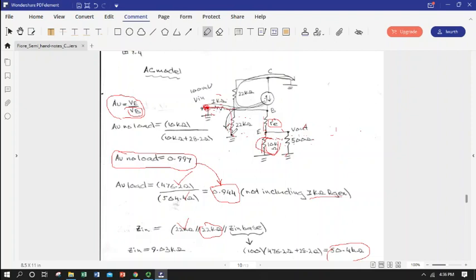Well, I can flow through the base resistor, so that's 22K, so there's this one. I can do this funky path through the base input of the transistor, where I have to multiply by the beta, my Zin base, but I can also get to ground by flowing back up to the collector, because that bias voltage source at the collector is no impediment to an AC signal, and I can flow to ground through the DC supply at the collector.